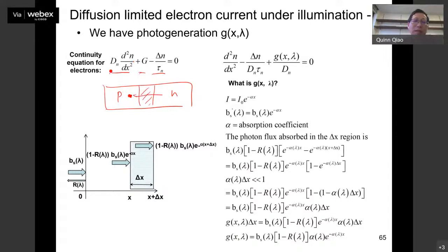That's by diffusion, right? And then how much generation, how much light absorption, right? At this position, how much accumulation, how much recombination, right? And then you have photon emission, that is radiative. There are other kinds of recombination, right? So basically, three mechanisms: one, diffusion; second, generation by photon; third, recombination. That's why you have these three parts.